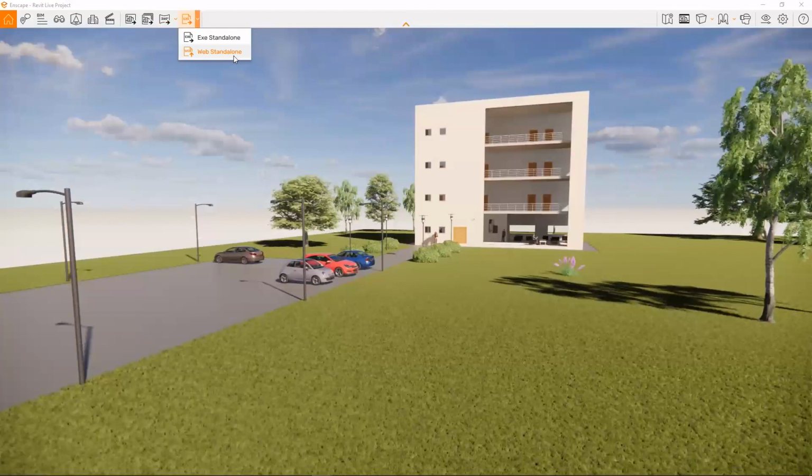With all these renders, if you store them on the cloud, so having an Enscape license, you have access to an Enscape account and you have storage space on there, you can upload your renders, store them on the cloud, and you can generate a QR code. Scanning that QR code on any mobile device will access those renders that you've created. Okay, so that kind of covers most of the visualization side of Enscape there.